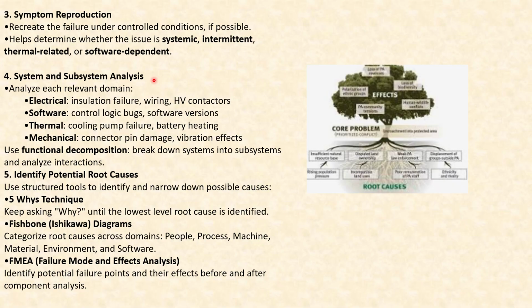Now, talking about symptom reproduction, recreate the failure under controlled conditions if possible. This is not a mandatory step, but usually it is preferred to recreate the failure under controlled conditions if possible, and that helps to determine whether the issue is systematic, intermittent, thermal related or software dependent. So at least you can identify what is the vertical which is responsible. Is it a systematic failure or intermittent failure, or whether it's connected to thermal aspects or software dependent. You can at least find out a vague area on which the symptom is dependent.